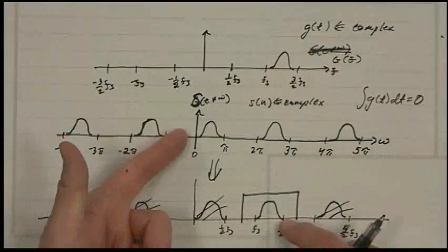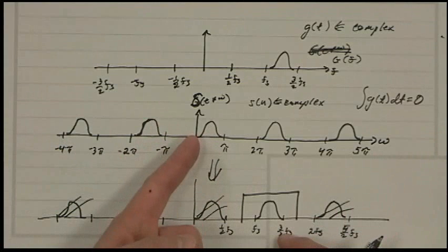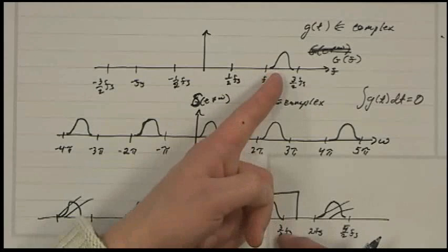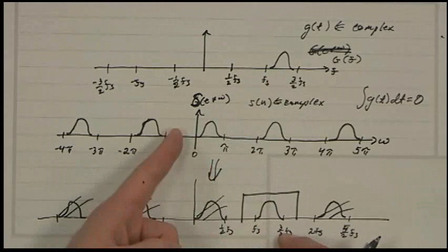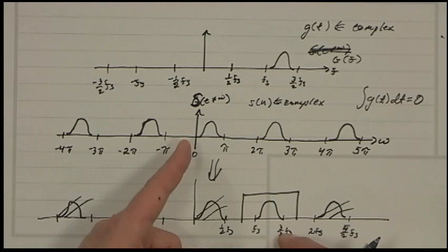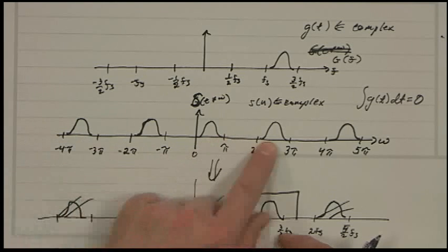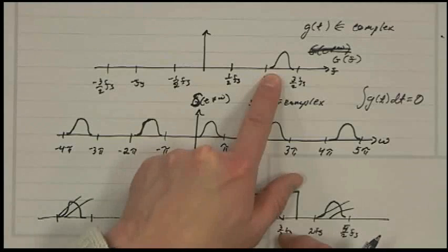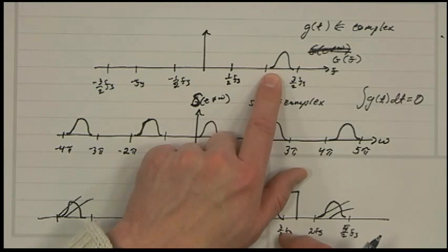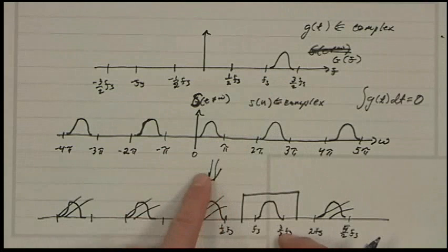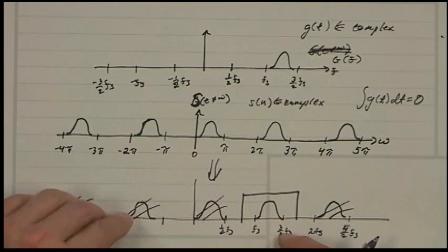So this is actually very important because you can actually demodulate a signal. Because this could be a modulated signal. You can demodulate a signal with sampling. But to do that, you have to have a very fast sampler because it has to be able to have an aperture that can sample at the carrier frequency. So usually what you do is you demodulate first because that could be more cheaply and stably done. And then this may bring it down to the IF frequency, they call it the intermediate frequency, and then sample that. And it gives you more accurate separations of what they call I and Q channels.